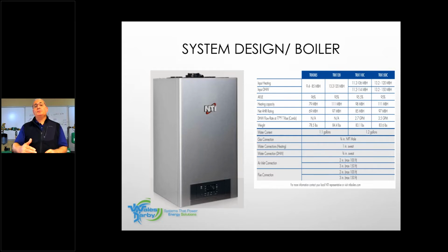Maybe an indirect would be better because we would build up the ability to have some storage available. So if multiple showers are going to be used at once, I've got a dump load and I've got recovery time built into it. We'll bring that up a little bit more as we go into this program about how to figure out recovery time. All right, we'll do that. So everybody should be feeling pretty good about that.